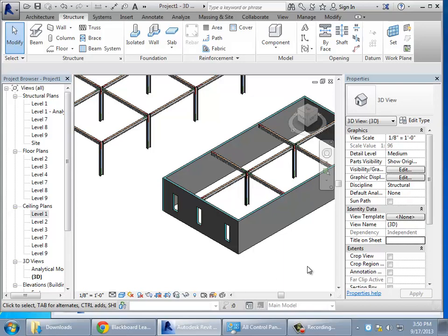So this is great for the main columns, it's great for the main girders that float around. Typically what happens at the next level is we're going to go through some intermediate beams, because the intermediate beams are going to span between the main girders.